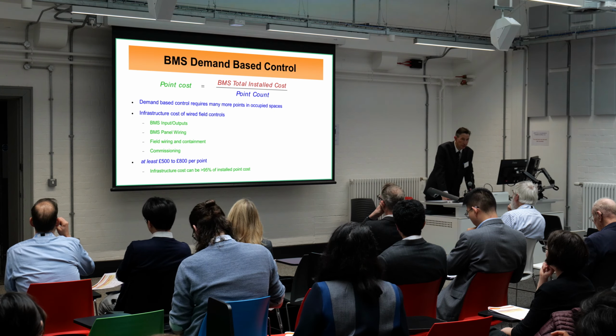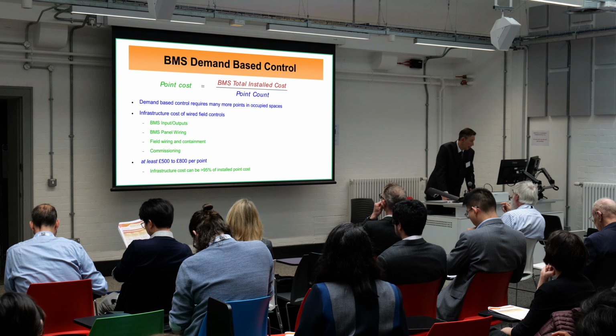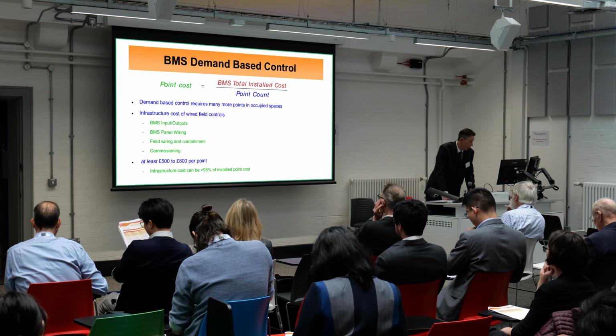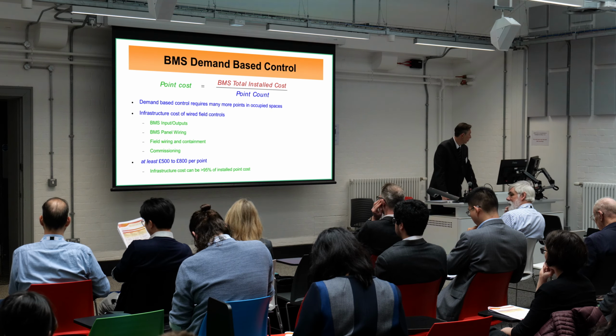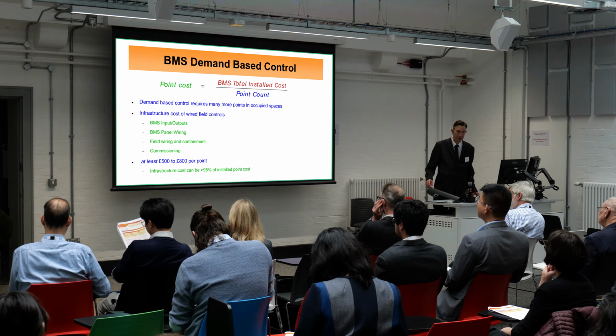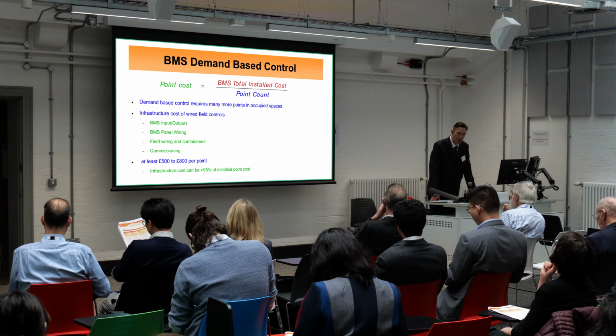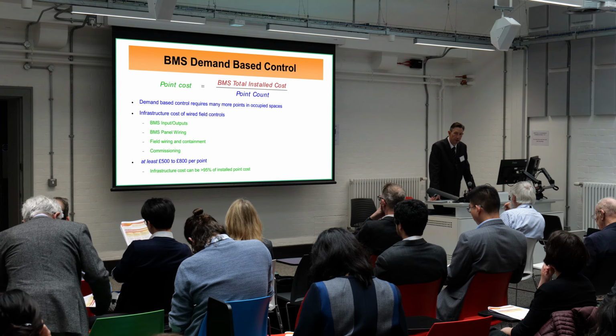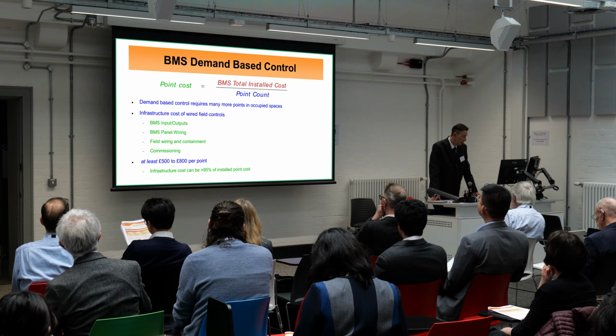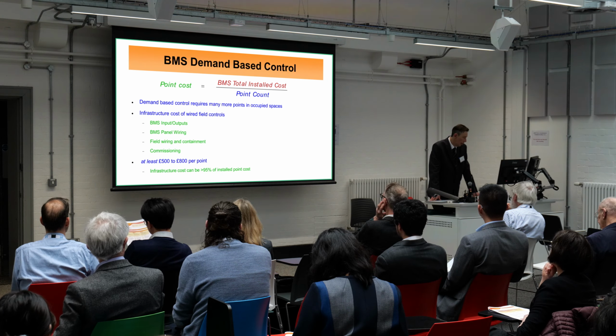How much does it cost to put a room sensor, for example, in a space and make that data available to the BMS? So we've got a room sensor in here somewhere. It probably costs about £10. But to actually make that data point visible in the BMS can cost several orders of magnitude.